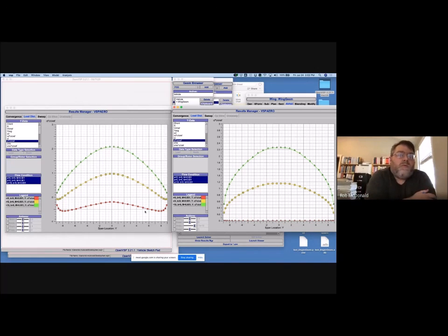what this really means is when you twist a wing, right, when we put 10 degrees negative angle of attack out here at the tips, it made this change to the basic lift distribution, right? It brought that down, negative at the tips, positive at the root. And it changed that shape, but you're not changing the deltas between it. So there's a lot of things that flow from that.